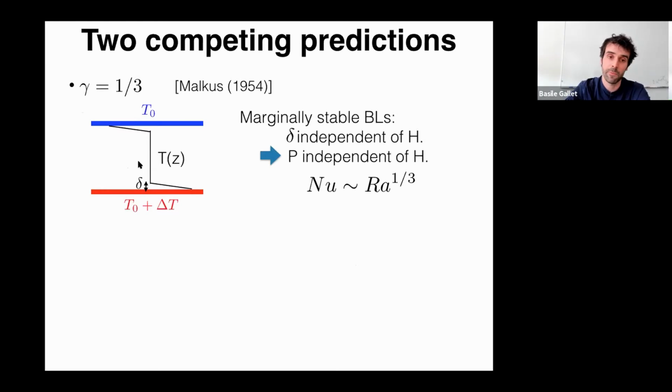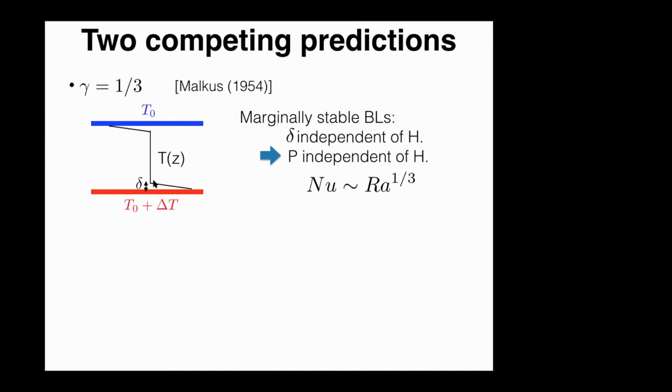The idea is the following. Well, indeed, if you force the flow very strongly with a large temperature difference, the flow will be fully turbulent. That means that you're going to mix the temperature field by vigorous turbulence in the bulk, but you still have a no-slip boundary condition at the two plates, so you won't have much fluid motion in the boundary layers near the plates. Which means that if you want to transfer heat from the hot plate to the cool one, well, first you need to diffuse that heat across the boundary layers, okay, before it's efficiently transported by the turbulent flow. And in fact, this diffusion across the boundary layers will be the limiting process of Rayleigh-Benard convection, according to Malkus.